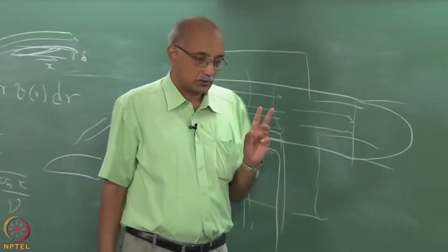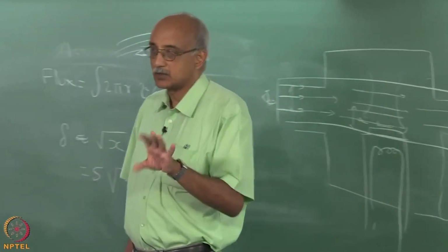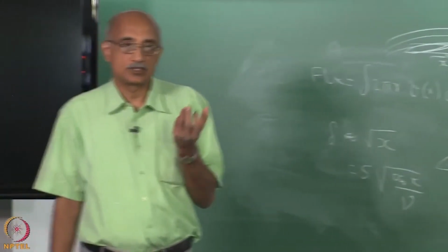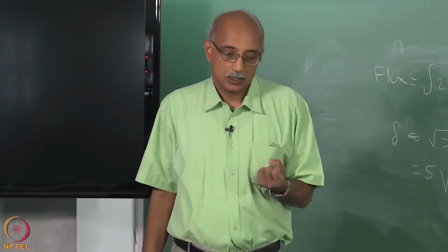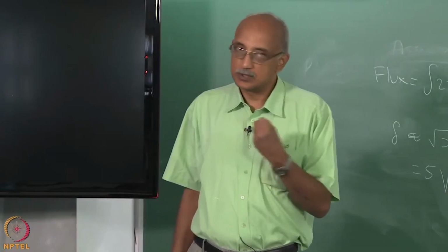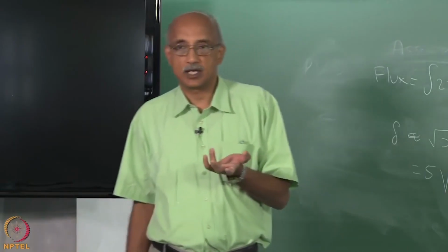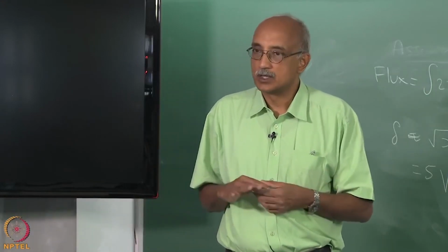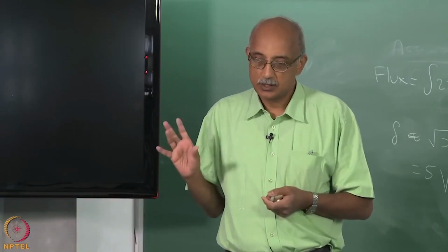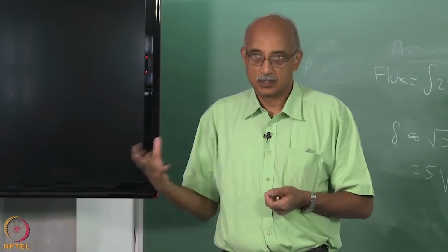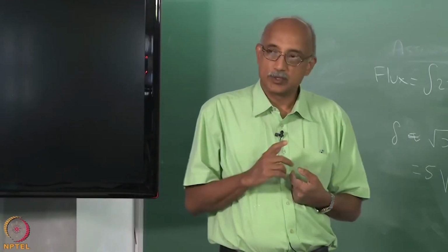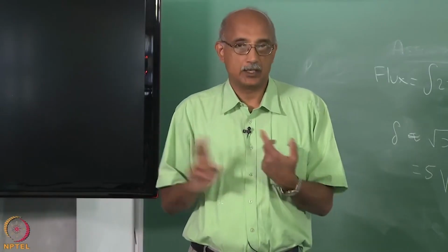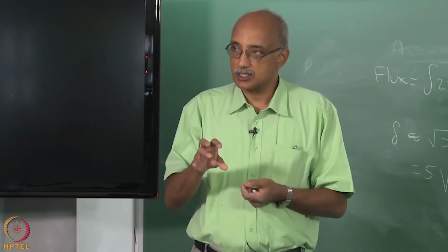So, we have touched a little bit on the thermodynamic side, touched a little bit on the transport side. So, when you are trying to model a CVD reactor in terms of its transport and thermodynamic properties, essentially the way you would want to do that is using CFD. I mean, computational fluid dynamic programs for modeling a CVD reactor are available. In fact, most of the commercial CFD packages will have a subroutine for CVD phenomena, but the way that they do it sometimes is not accurate, because they do not take into account the two-way coupling between the chemical reactions and the transport phenomena.